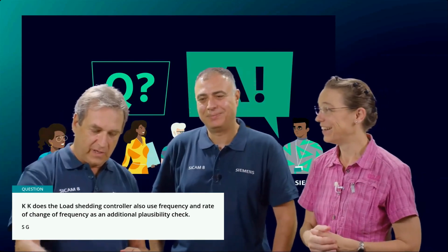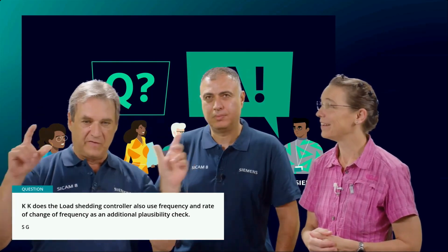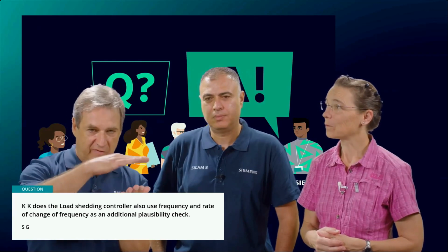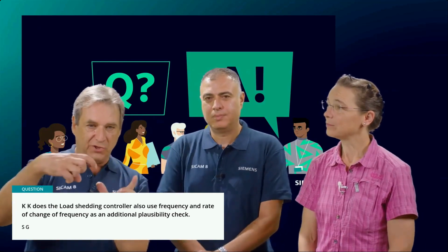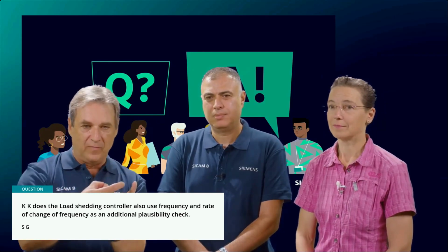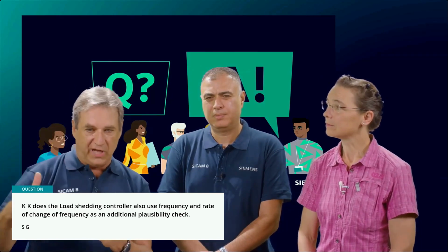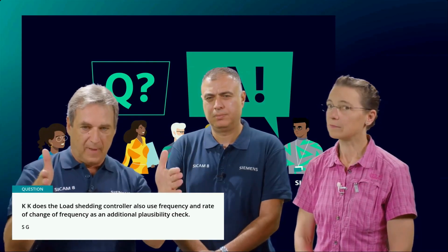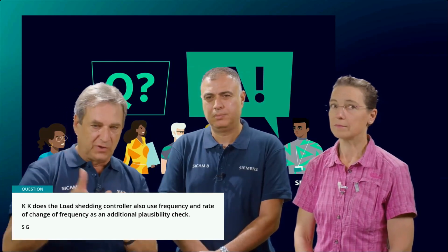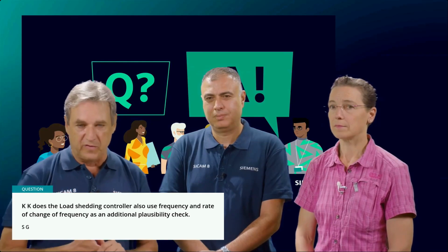Maybe you have noticed several times we have also used the expression frequency stage. A stage is a combination of the frequency itself and a certain duration of the frequency. For instance, if the frequency stays at a certain level for a certain time. And the third thing that you can also consider is the gradient, so the rate of change. That's a stage. That's normally what we consider. Of course, additional functions like a plausibility check can also be done. It's not really our standard, but it would be possible, of course.